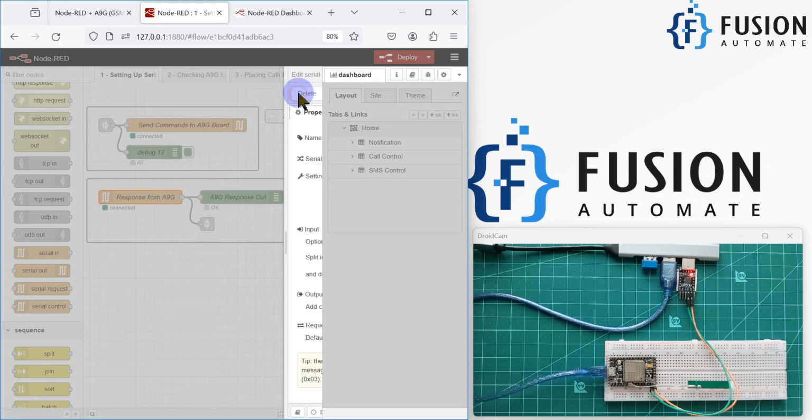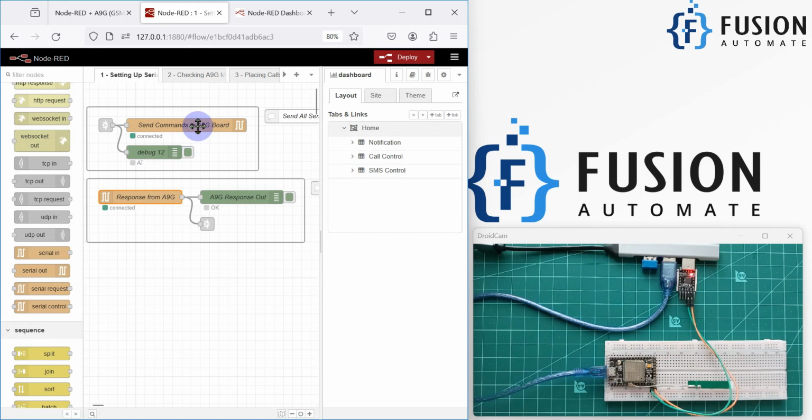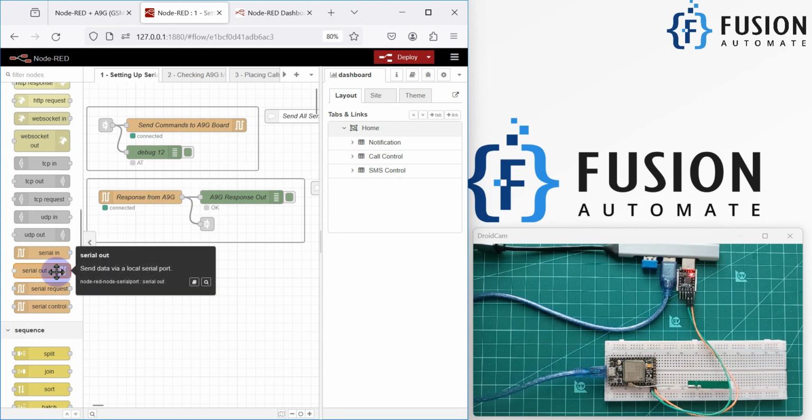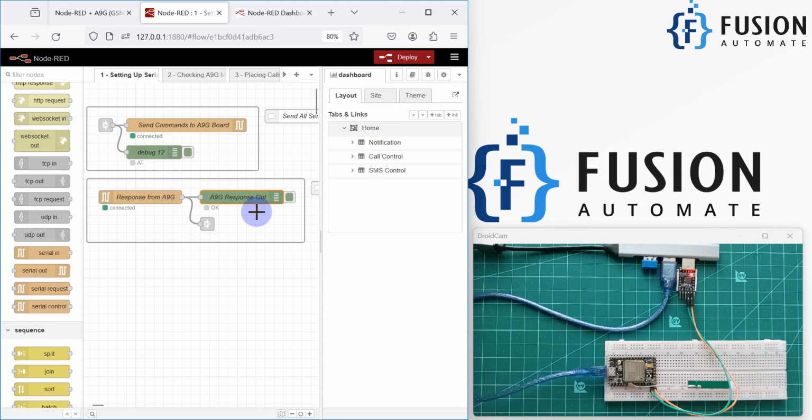And that's it. We have configured two nodes to read data from the A9G board and to send data to the A9G board. Whenever you want to send data to the A9G board, we use the serial out node, and whenever we want to read data from the A9G board, we use the serial in node. And here is the debug node, which is used to show what we are sending and what we are receiving from the A9G board. So let me deploy it.